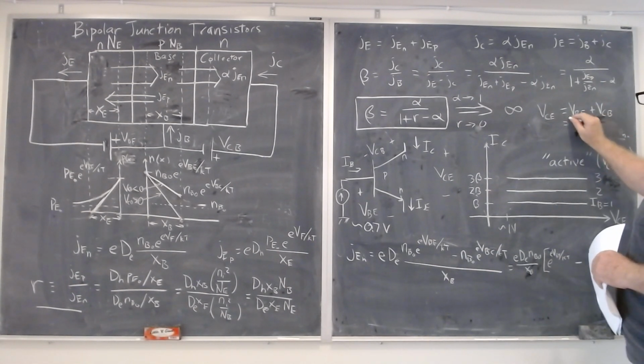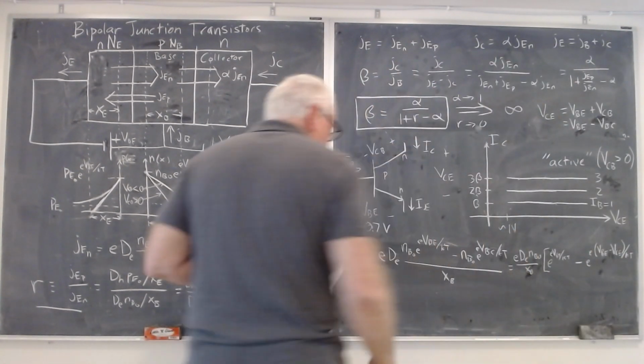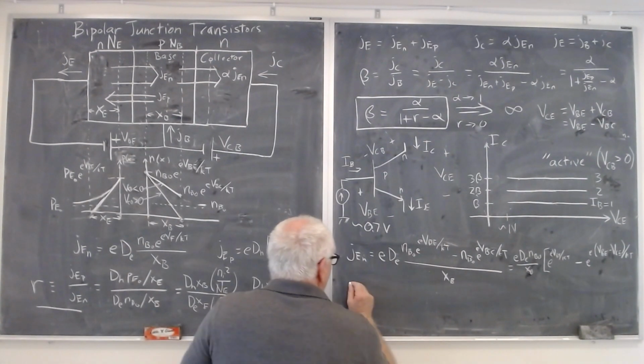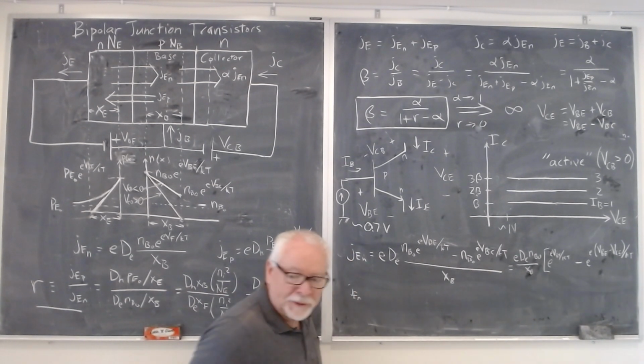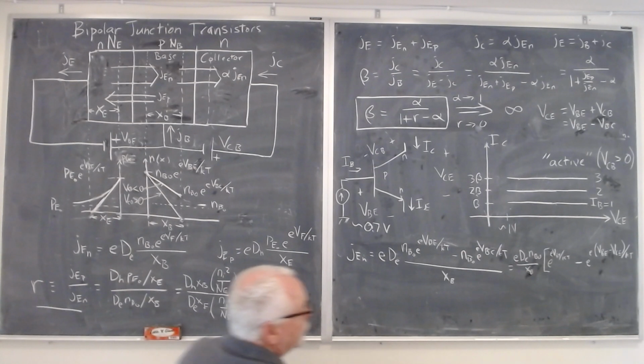And you just have to realize that when I reverse the letters here, because in this formula I want the voltage of the base with respect to collector, I just put a minus sign there. So now down here, I can substitute for VBC. VBC is equal to VBE minus VCE over KT. And you'll see in a minute why I did it that way. I tried to plan this all out in terms of the available board space. So now I can write this very neatly. I forgot my bracket over here.